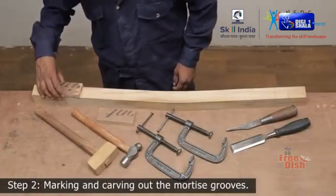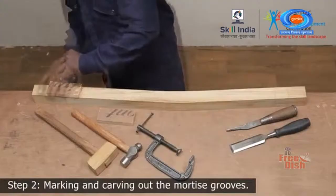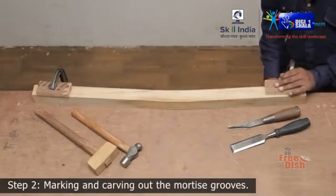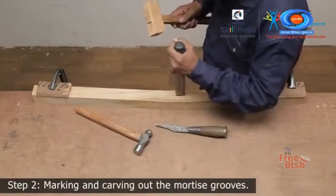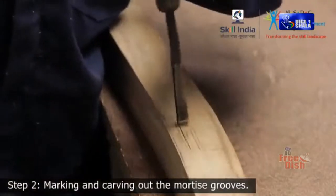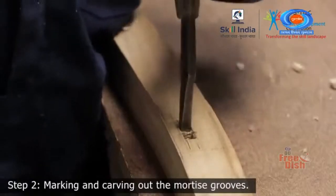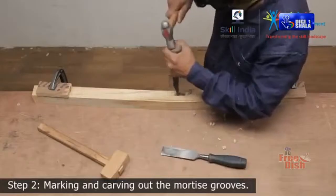Secure the back leg to the workbench with a G-clamp. Remember to place a piece of scrap wood in between the clamp jaw to avoid marring the workpiece. Now with a mortise chisel and wooden mallet, chisel out a mortise. Remember to keep the mortise edges inside the depth clean and sharp, as the tenon will not be a perfect fit if the edges are rough.